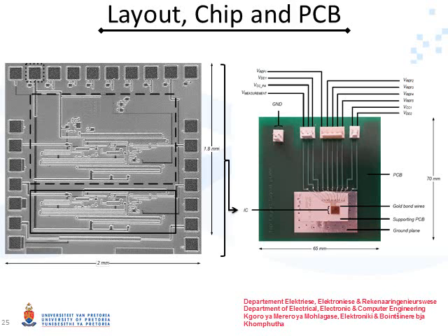The IC was first baked onto a supporting PCB, and gold wire bonds were used to connect the PCB pads to the bond pads on the IC. The supporting PCB was then placed onto a larger PCB as shown in the figure on the right. 3 ICs were mounted onto 3 PCBs and on-wafer probes were used to conduct the measurements.